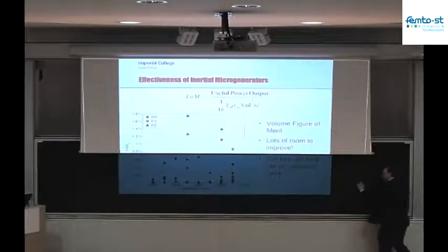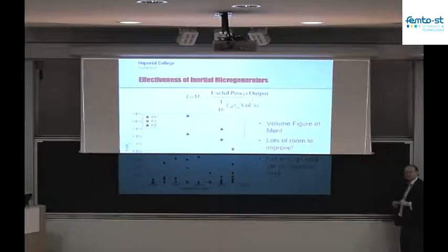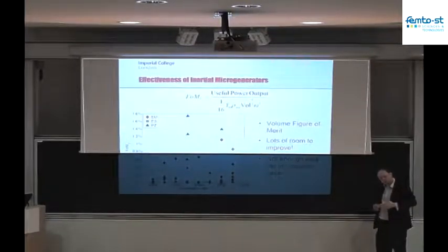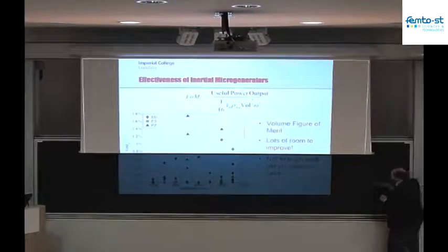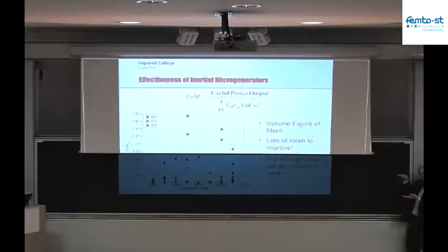So it's displacement. If this is now displacement that I'm thinking of, and this is the displacement of the mass that is moving, then the fundamental component of this waveform here, that's a little bit shorter because the top is being taken off it by the third harmonic, the fundamental component of displacement is the same as it was here. But the actual distance that is being traveled by the mass overall is a little bit less because the third harmonic is cutting that down.